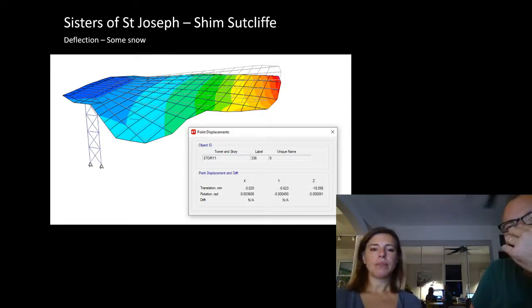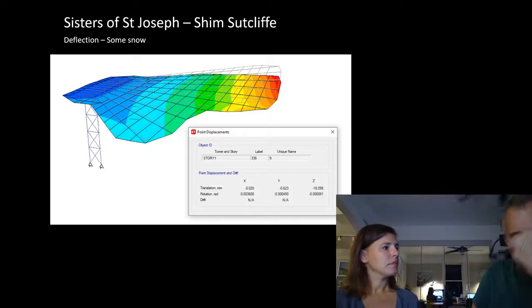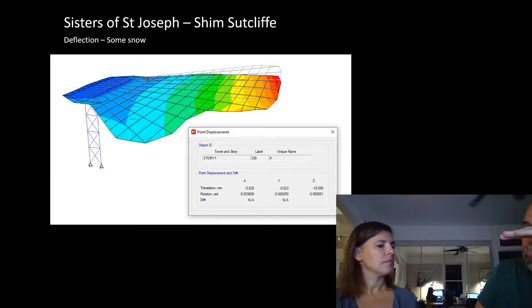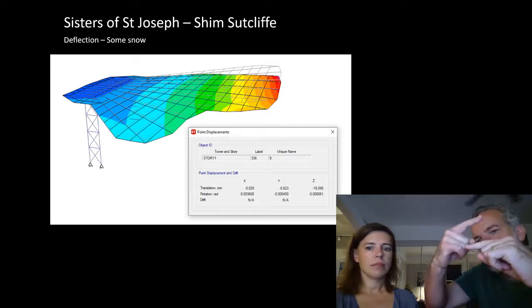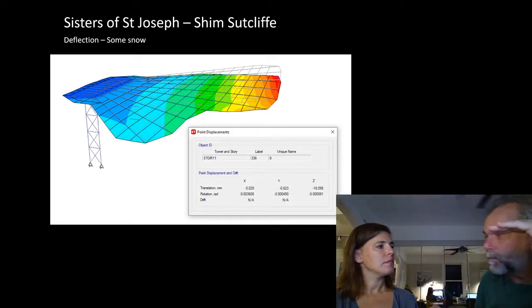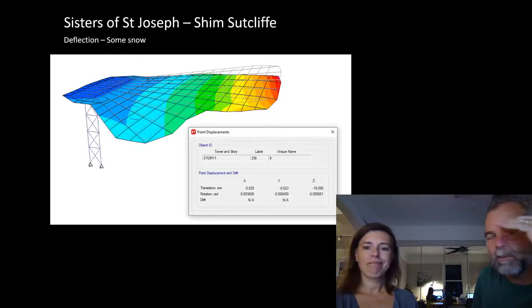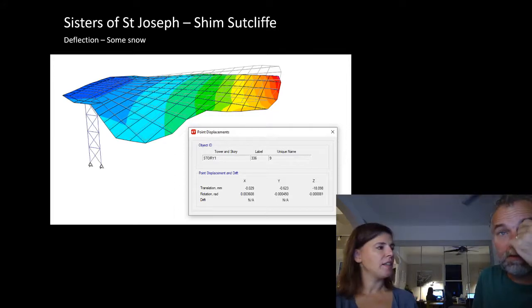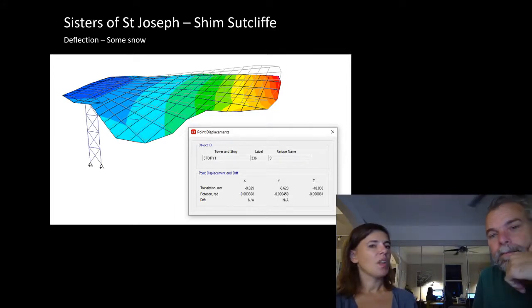It's a really important point that you just made: if you have a straight canopy that is parallel to the building, then your eye can pick up where things are no longer parallel, and that becomes apparent to you. You can really read the deflection. Where you've got a curvilinear shape around the perimeter like this, it could deflect 200 millimeters, and your eye would not be able to tell. It would be so hard to see.